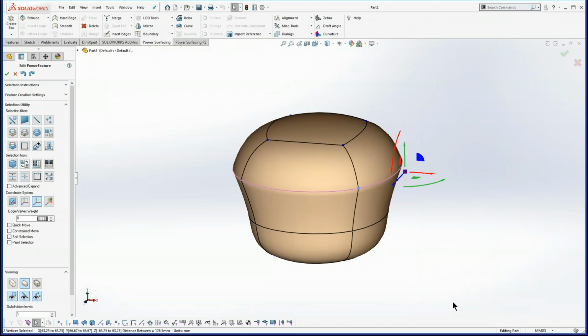The key with 3ds Max is that it has a couple of different polygonal modeling systems. You can model things with triangles, or you can model with quads. And the things that are modeled with quads will come in easier than the ones with triangles. So typically the ones that are done like sub-D models using what's that called? Mesh smooth. Mesh smooth, yeah. Anything that has the mesh smooth on it comes in pretty well. Although you usually want to tell it not to have the mesh smooth already on it when you bring it in. Correct. Bring it in with a control mesh and we'll round it because it does the same rounding basically.